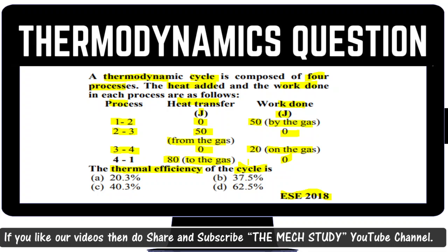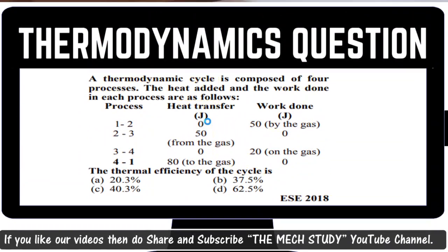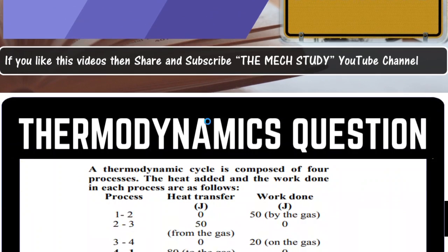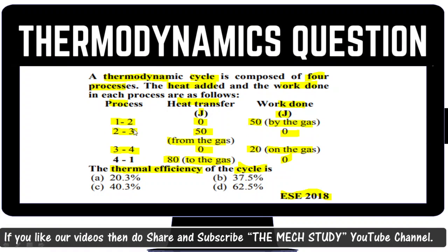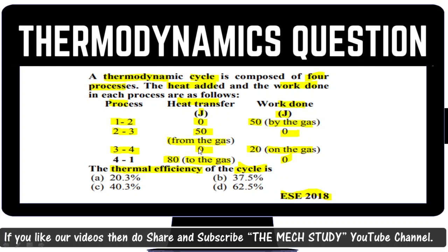Going ahead with the solution, they have mentioned heat rejected in the question. Heat rejected by the system was 50 joule from the gas, and that's why they have considered heat rejected with a negative sign. From that perspective, heat rejected Q2 is 50, and similarly heat added is 80 joule, which they have taken from process 4 to 1.